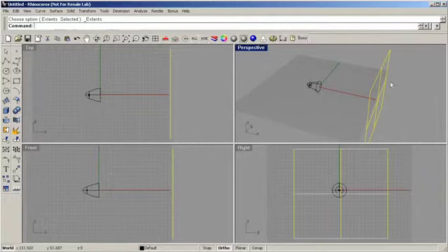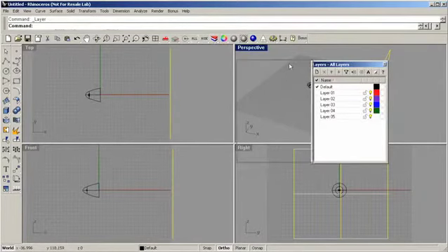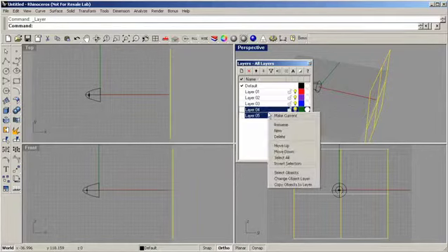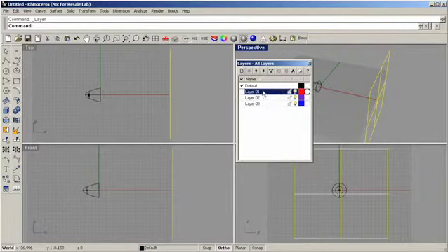Now at this point we can export geometry over into ASAP, define and assign optical properties, and run the ray trace. However, for complex CAD models, it's much easier to do that if objects are layered according to their optical properties. Just as an example, even though this is a very simple system, I'm going to show how that's done in Rhino. We're going to go up here to the Edit Layer dialog box, and I only need 3 layers here, so I'm going to delete the last 2, and I'm going to rename these layers.